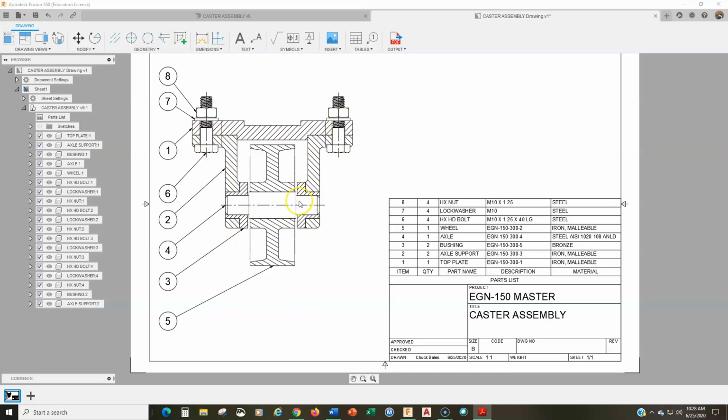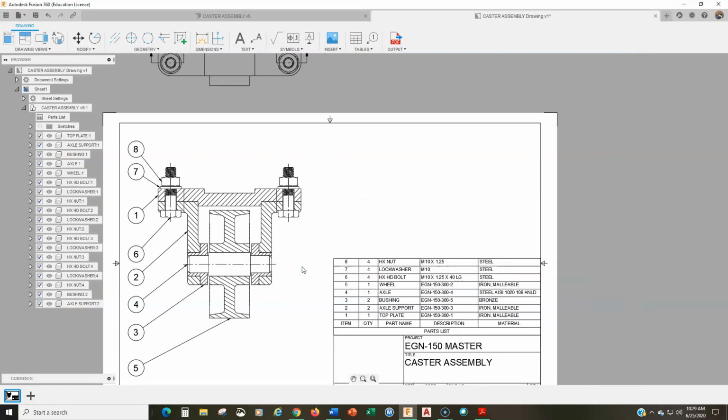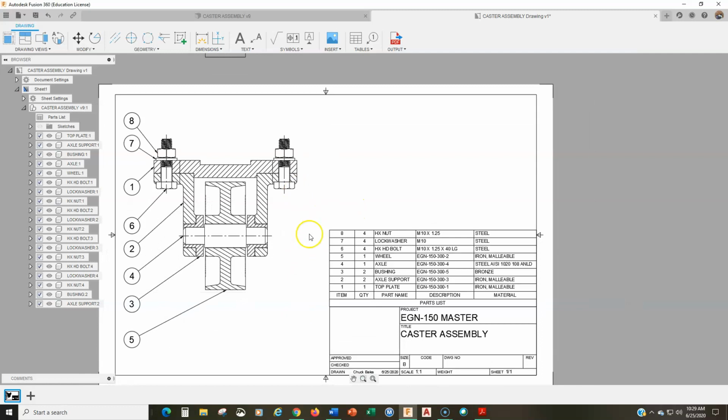There are actually no dimensions in this, so we do not need a dimension standard note. All right. So you need an all dimensions in millimeters note. Why millimeters? Because right here these numbers are in millimeters. That should be it.